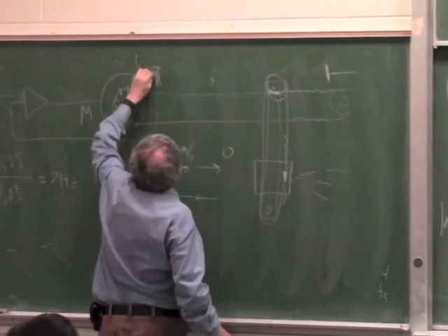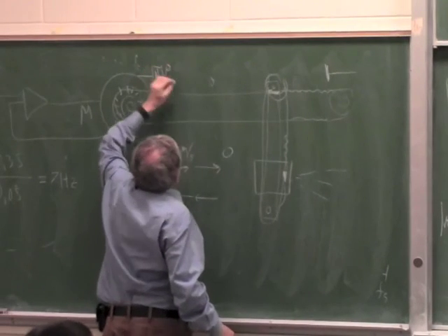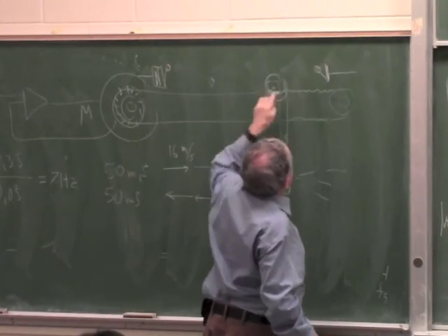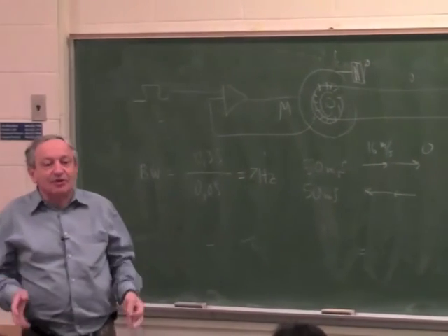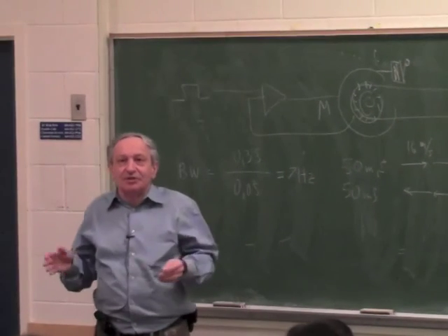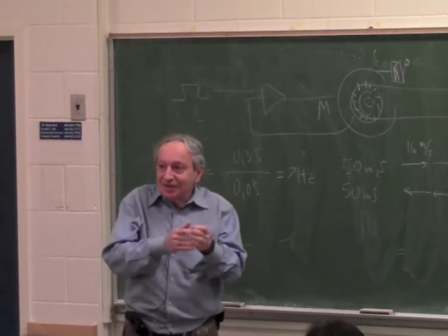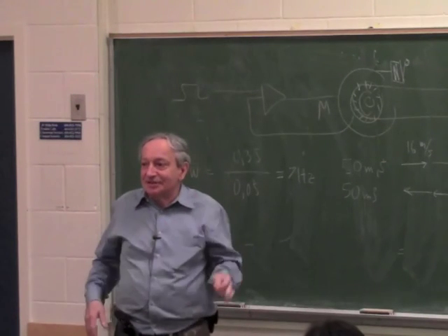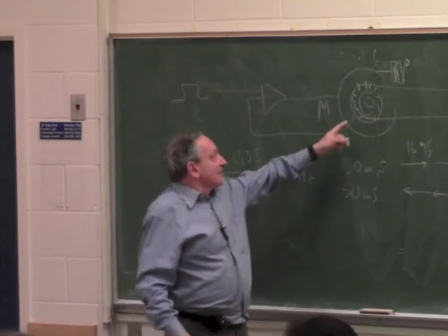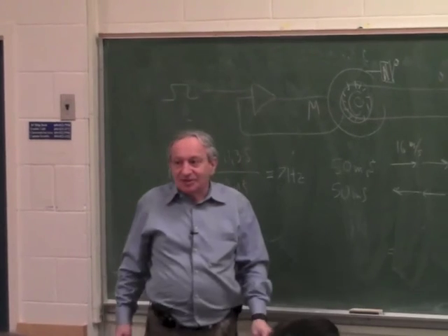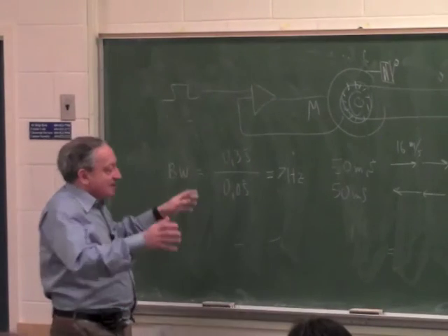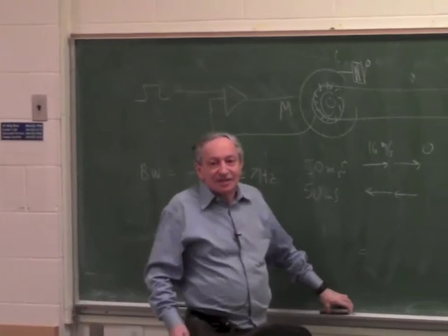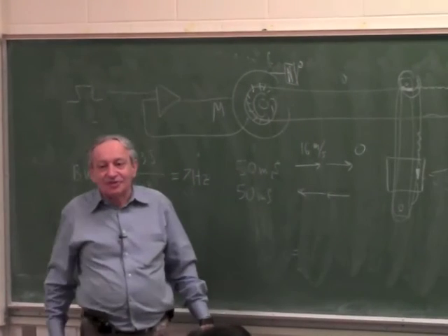They just have a micro switch here, because this sensor doesn't have to be that accurate. It just tells you it's end of travel. So when you turn on a machine like a CNC machine, it always goes to one end, hits the limit switch, and says calibrated. And then it measures with a non-absolute sensor. Okay?